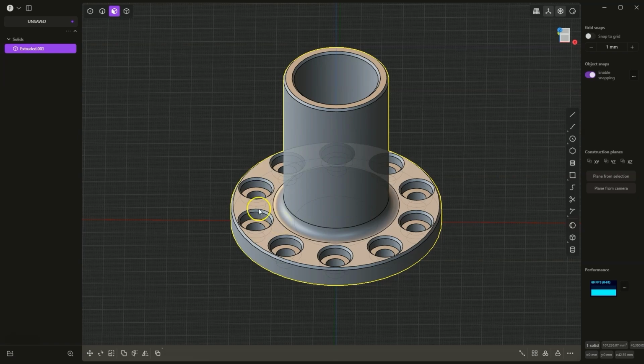If in the future, in the case of such a selection, you want to deselect some edges, you can easily do this. Just press the Control key and deselect the selected edges. However, in this case, you must switch to Edge Selection mode.